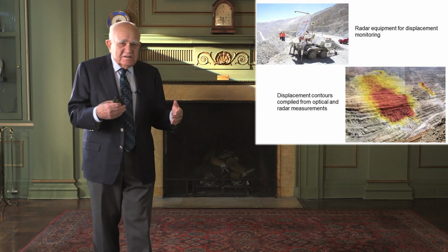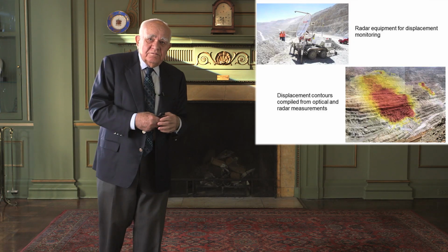So over the years, the techniques for monitoring and modeling have gone hand in hand. And the net result of that is a process where if you know that there is instability, you can plan to do something about it. You can plan to divert your mining activities, to take the failure out, or do various things. You can't reinforce it on this scale because the slope is simply too large.